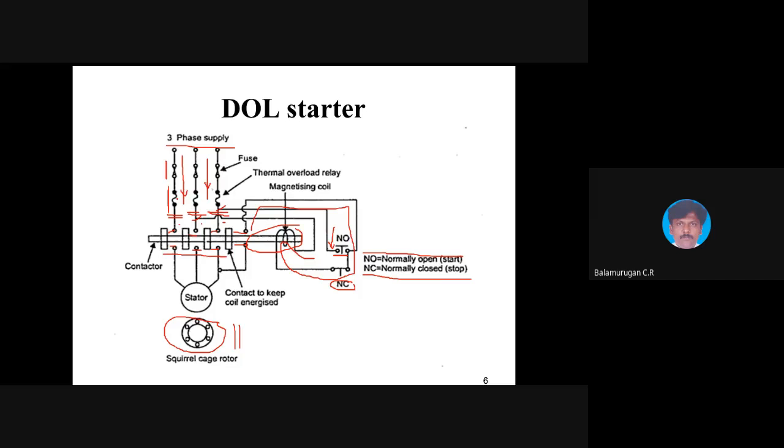Here ST represents the starting and F represents the full load, with SF being the full load slip. With reference to the previous equation, the full load torque will be equal to K IF squared divided by SF.